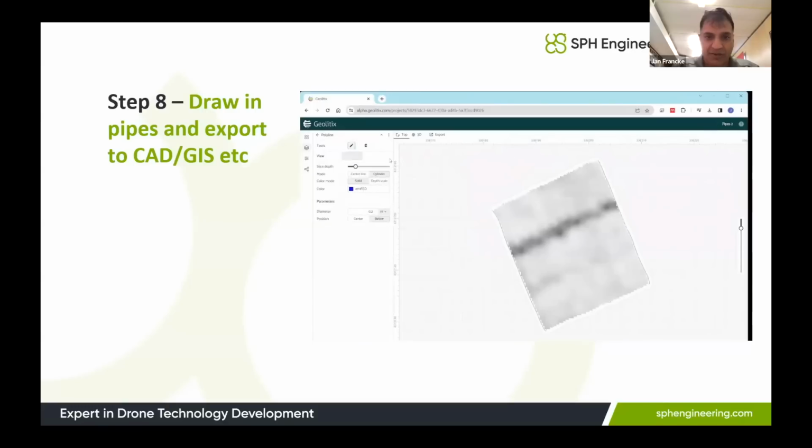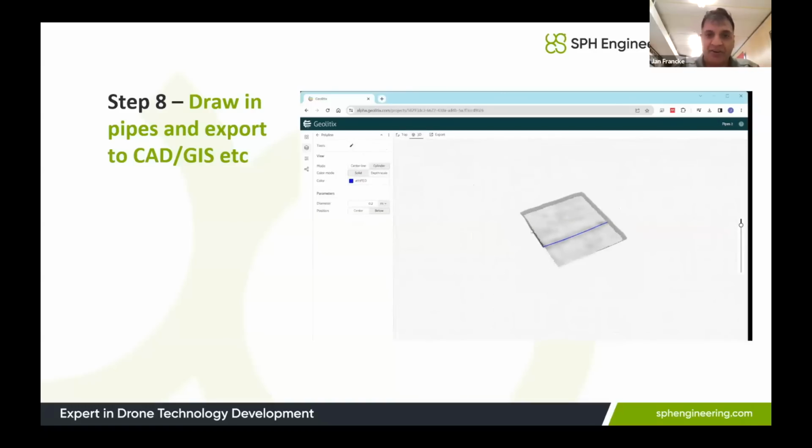So here we go. We're going to start at one side, and of course, if it bends, we can add a few intermediary points, but it really is just drawing in the lines. And then let's go to another level. Let's drop down to, or maybe it's slightly higher up. Yep, there it is. Okay, so I'll grab that one, find the top of it where it first appears, draw in another pipe. I can be very precise about this, and that's it, right? I've now created my pipes.